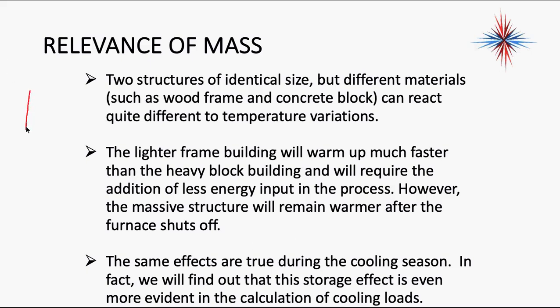Let me give an example of that. If I have a 2x4 wall, okay, and again, forgive my drawing, this is south. If the sun is beating down on this wall, it's 2x4 construction. Sun hits it pretty much from, let's say, 1 o'clock to 4 o'clock in the afternoon. The heat's going to come through this wall relatively fast. 2x4 construction, it's not thick. Okay, but once the sun goes down, this wall is going to cool off really quickly, and eventually heat will start moving the opposite direction as the evening cools down.